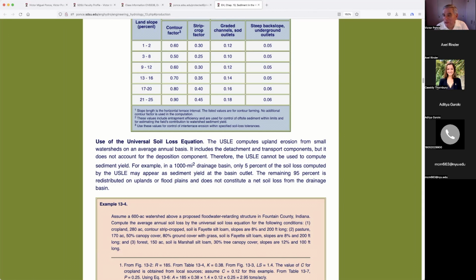There are exceptions. Under a normal situation, the gradation of the bottom of a river would be continuous, meaning big rocks upstream, little sand downstream. And even if you get to the estuary, it wouldn't even be sand, it would be silt. So you go from big rocks, boulders, to gravel, to sand, to silt, as you move all the way from the hills to the estuary. Is that 100% correct?